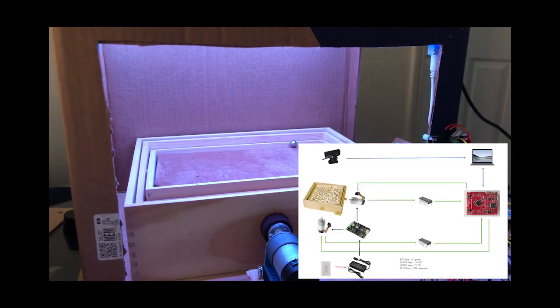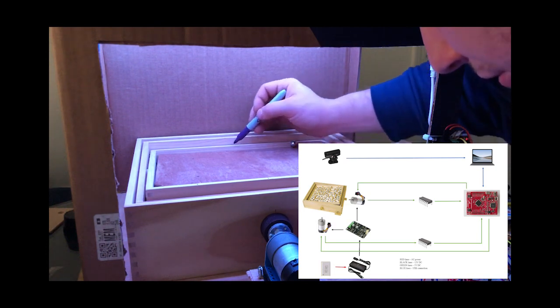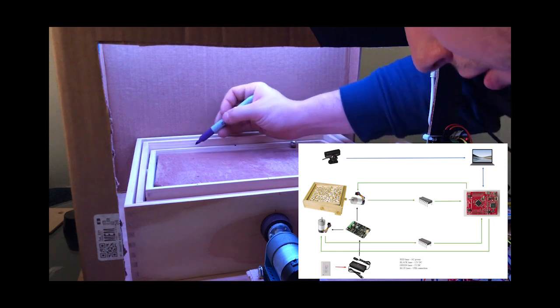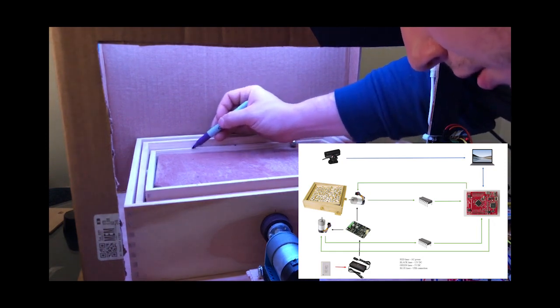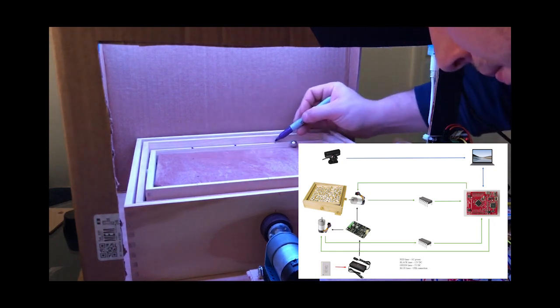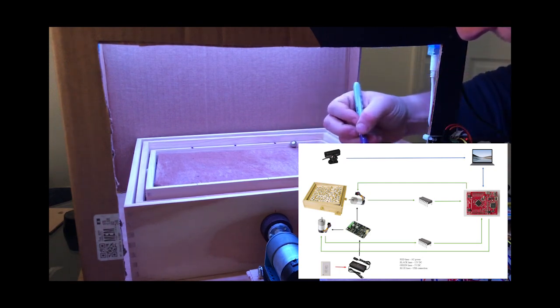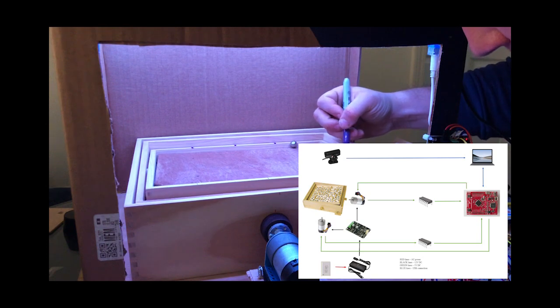A wall adapter is used to power the motors and H-bridge. The H-bridge is used to control the speed and direction of the motors. The motors have encoders on them to determine when the motor is turning. The amount the motor is turning is then counted using two counter chips and sent to our microcontroller to be used in the motor controller.